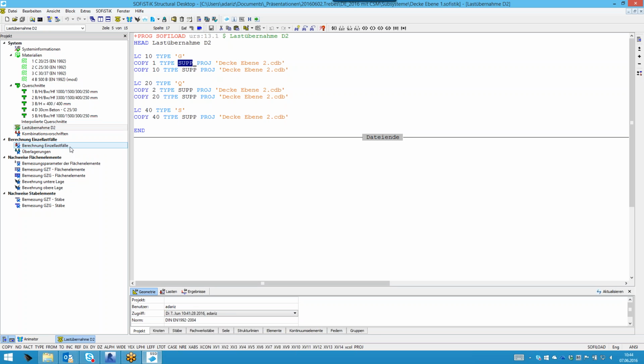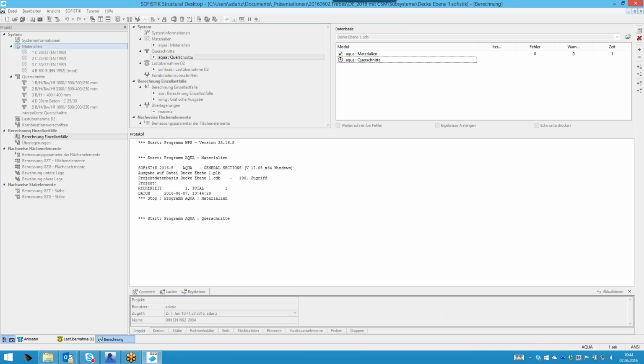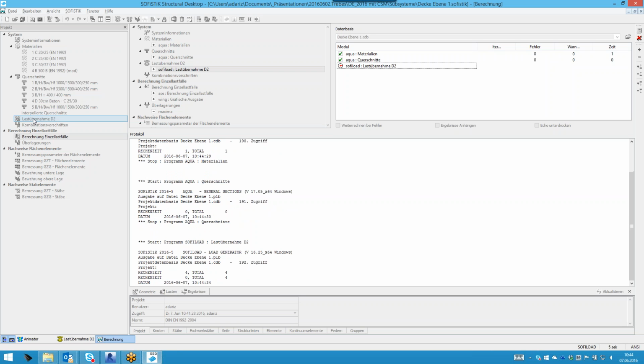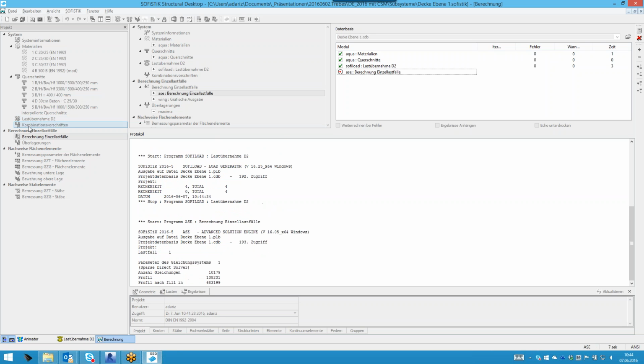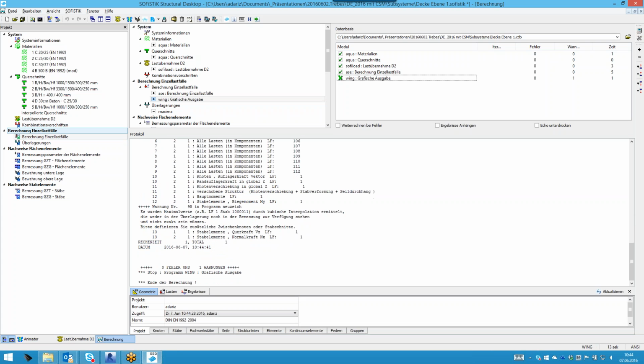So we get the entire load takedown directly in this 2D subsystem database, and when we calculate this text task, we extract all the loads from the subsystem above and apply them on the database in addition to the loads coming from Revit for this subsystem.